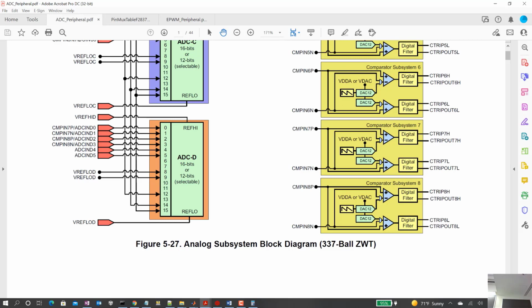The other thing to know, and again, really not important to us, but putting ADCs on a high-speed microcontroller is actually very difficult on the analog end of things. It's about not getting mixed in with all the noise of the processor. Bits are going high, low, all the time. Clocks are going up and down, all the way up to 3.3 volts, back down to 0, right? That causes bouncing of ground, that causes noise.